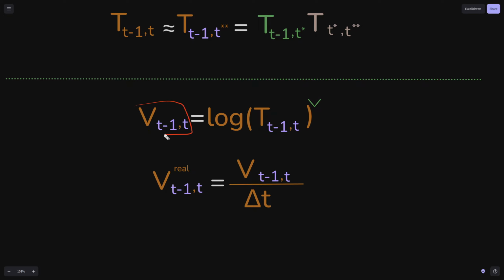Because this Lie algebra comes from this story that you move from the identity to this in 1 second, but you don't move in 1 second, you move in delta t. And this is the implementation. Your robot will have its own delta t, which is of your choice, okay? So basically, the real velocity is the logarithm divided by the delta t that you have, okay? Well, that's it. There might be other things I could comment on, but I think it is enough for now.